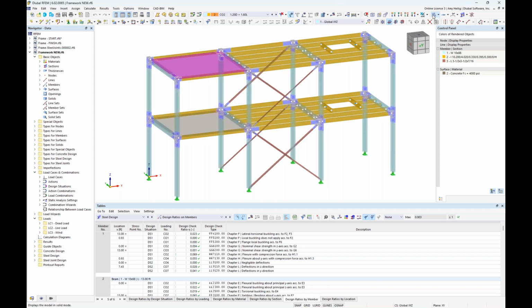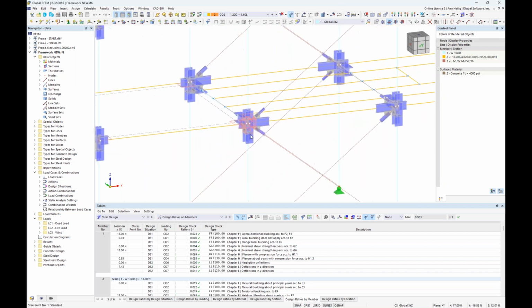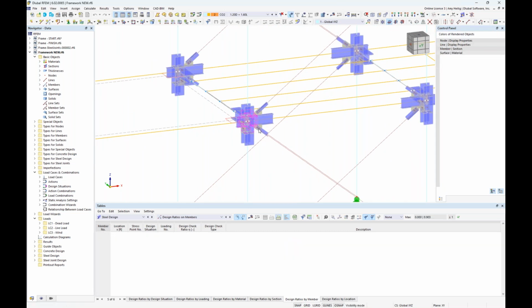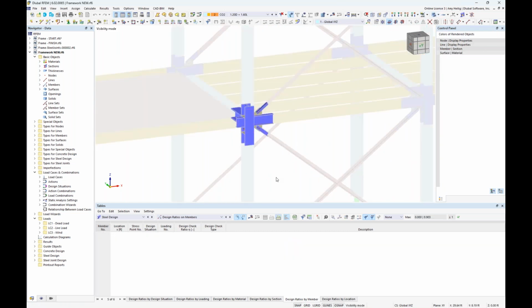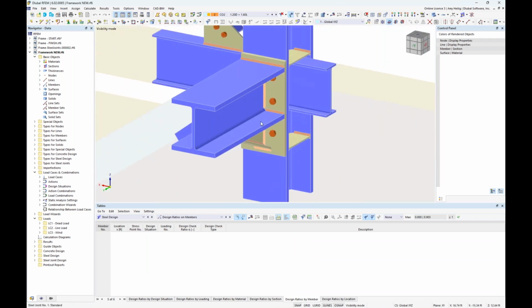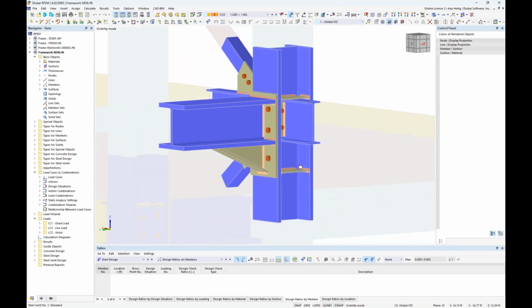And if I go to the wireframe view, what you'll also notice is that I have defined these joint connections at all of the major intersections here of our steel members. So if we take a look at maybe one of these particular connections, I'll go ahead and create a visibility by this selected object, and let me turn this back into a solid rendered view. Well, when we zoom in here, we can see that this connection is certainly a little bit more complex than what we just saw with our 2D frame.